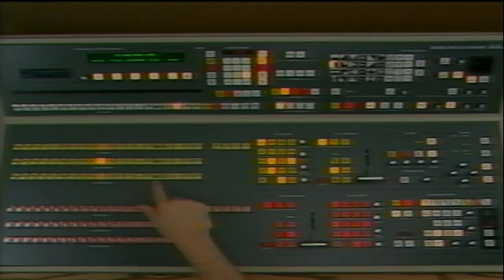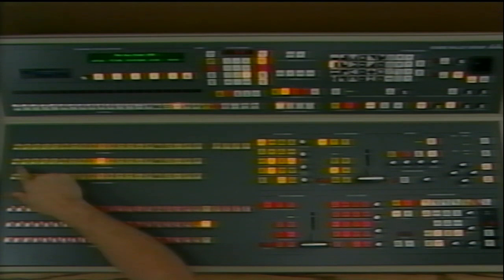The bottom or lower bus in Mix Effects 1 is the B background bus. This bus provides the next background source as a result of our next background transition. Above the B background bus is the middle row of push buttons of the A background bus, which is used to select the background currently contributing to that Mix Effects video output. The top row of push buttons, the key buses, provide control of the same 20 primaries common to the A and B background buses, and 4 additional sources are available as external key fills.